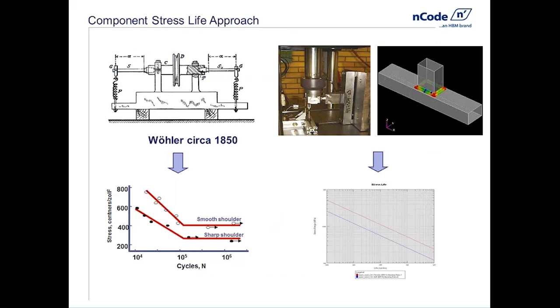The fact that we're utilizing stress measures that don't represent the actual stress at the toe leads us to use a damage curve that isn't really talking about material. We're not going to have a damage curve that's looking at the fatigue effect of the deposited weld metal or the heat affected zone.